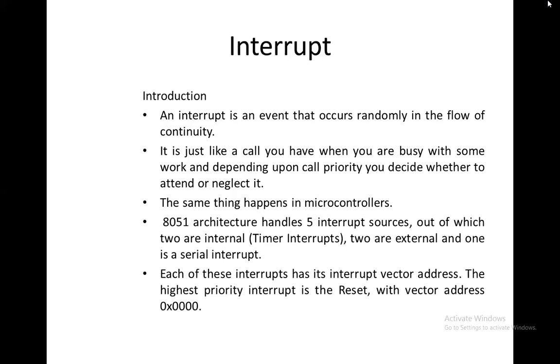So the 8051 has 5 interrupts. Two internal interrupts are there, Timer 0 and Timer 1. Two external interrupts are there, INT0 and INT1. And one is a serial interrupt, with RI and TI, where RI means receive interrupt and TI means transmit interrupt.